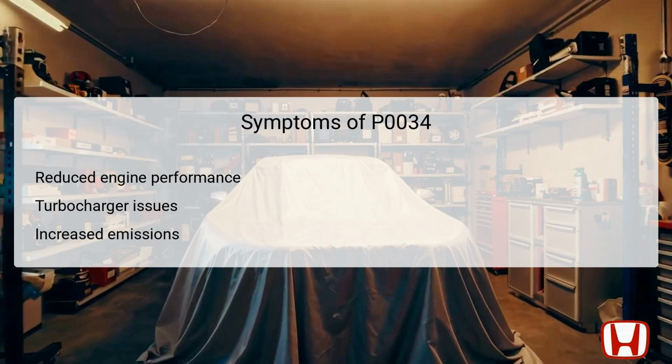Additionally, the driver may notice a decline in fuel efficiency because the engine cannot operate at its intended performance levels, burning more fuel. Increased emissions can also be a consequence, as the inefficiency of the turbocharger may cause the engine to run richer, releasing more pollutants. Observing these symptoms can provide critical insights during the diagnostic process.